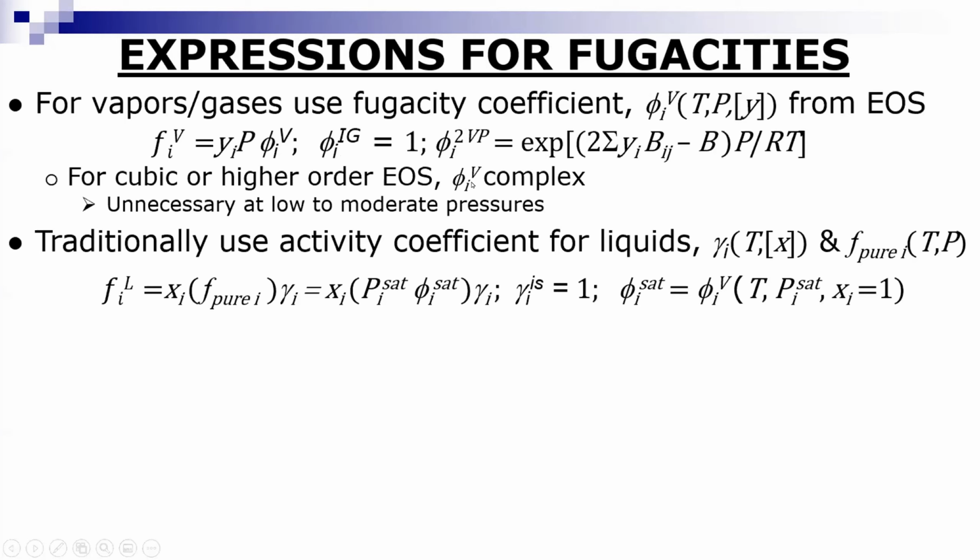For cubic or higher equation of state, the fugacity coefficient is complicated. And as I think Rafik implied, you don't always need to do it, and you get into trouble when you want to do complicated calculations. So one of the things you want to do is evaluate whether you really need to go to a higher order equation of state. Traditionally, we use activity coefficients for liquids, and the activity coefficient and the pure component fugacity.